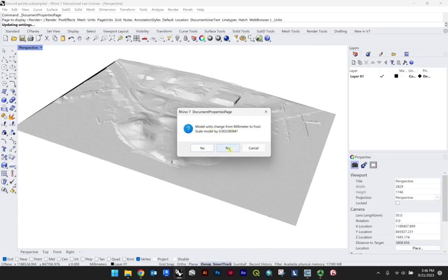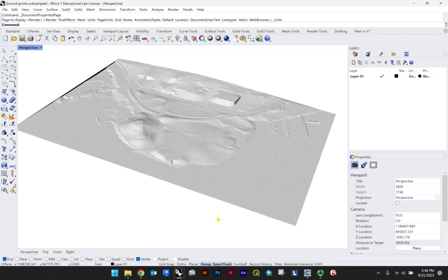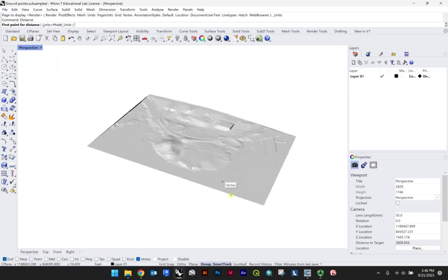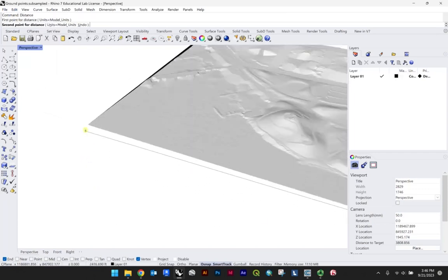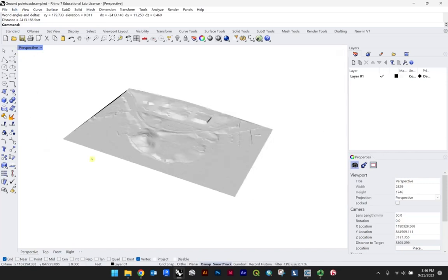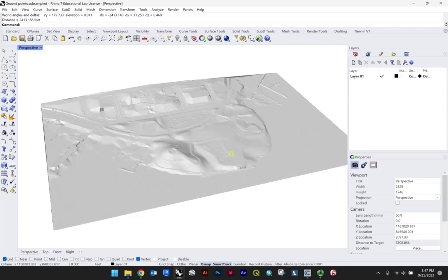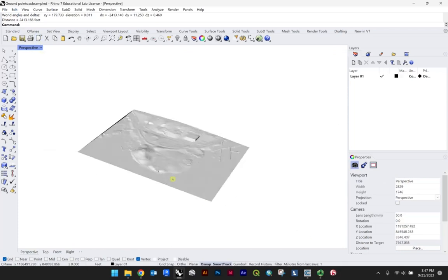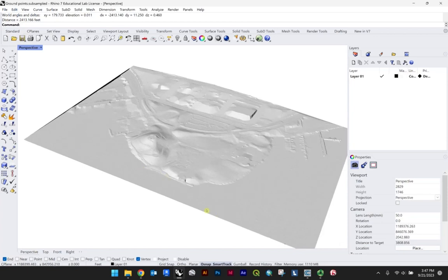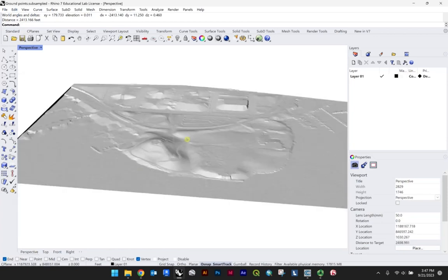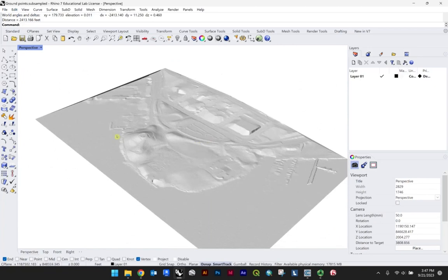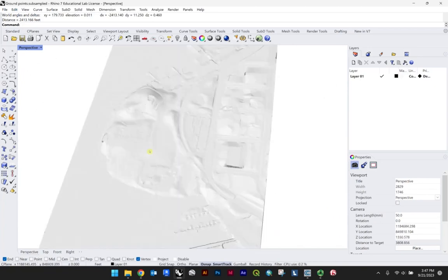And then because it opened in millimeters, let's not scale this model, because I imagine, let's see. Yeah, okay. I assume, what is that? 2,400 feet is maybe a reasonable distance. Certainly 2,400 millimeters would not have been even relatively close. So make sure you just double check your units as you're working through that.